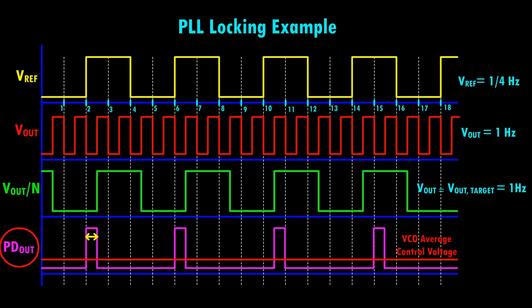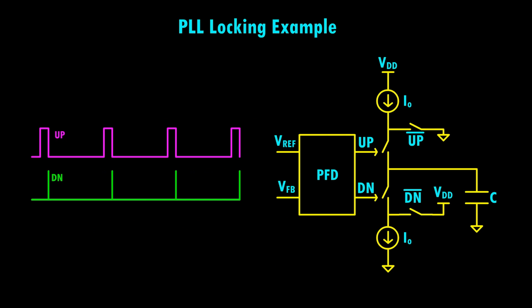This is necessary since the charge on the charge pump capacitor would gradually dissipate over time, and without these pulses, the voltage would drop. Therefore, periodic replenishment of charge is required to keep the voltage steady and maintain a locked state of the PLL.